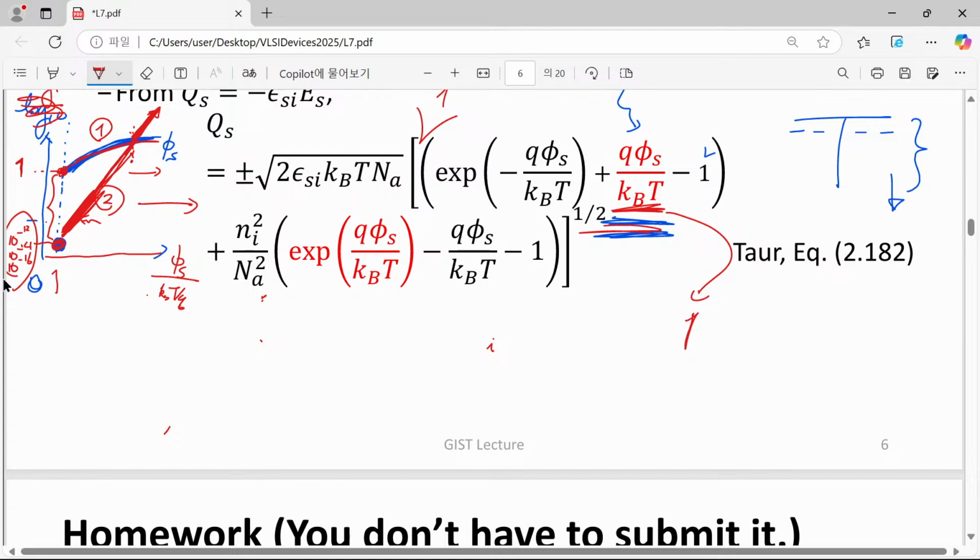As I told you before, it is actually not exactly this point. There is some point where we have a difference between mechanism 1 dominant and mechanism 2 dominant, and more or less their cross point corresponds to the threshold voltage, but not exactly, because there are many different definitions of threshold voltage, and today we will talk about one of them.